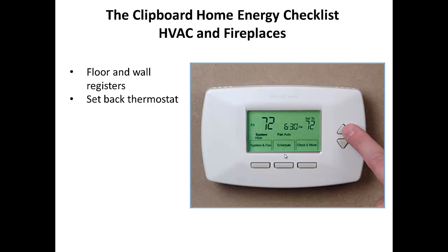The other thing is a setback thermostat, which is a great tool, because you can set that thermostat back at night. You can set it when you're gone during the day at work if no one's in the home, so it helps you manage how much heat your house needs. And you can set it a half hour before you come home, so that by the time you get home, the house is back up.